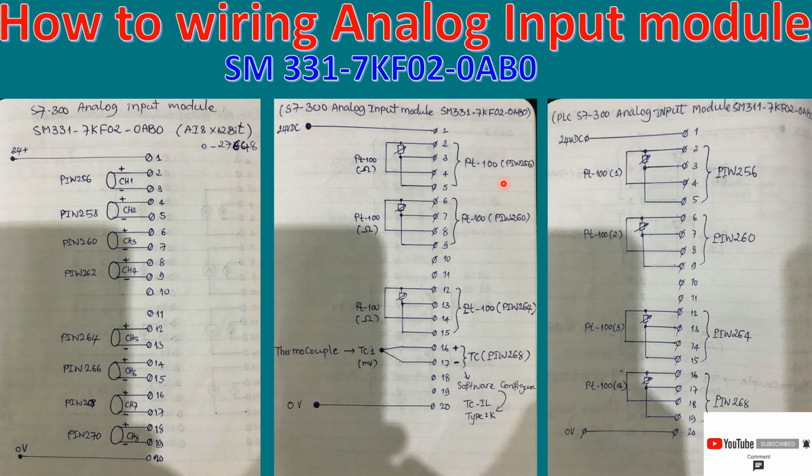And for option number 3, this is just combined with option number 1 and option number 2. So if we would like to connect with the PT100, we can use only 4 channels, and the connection is similar to option number 2.